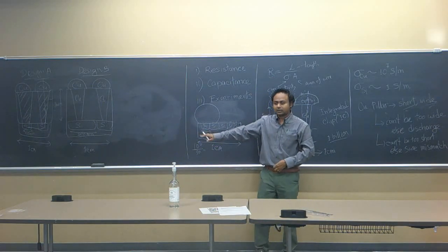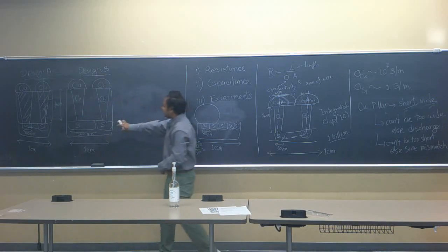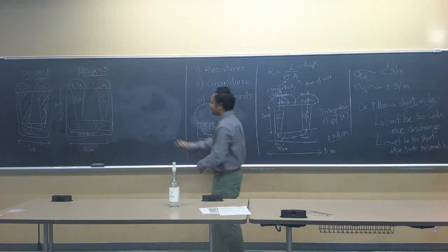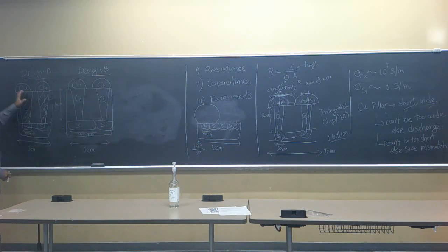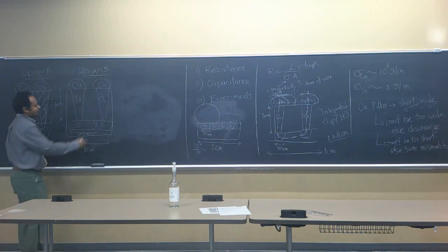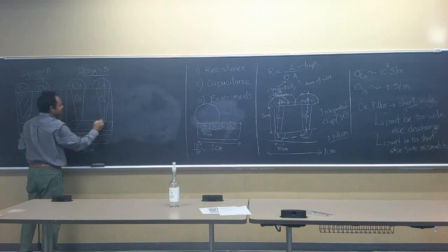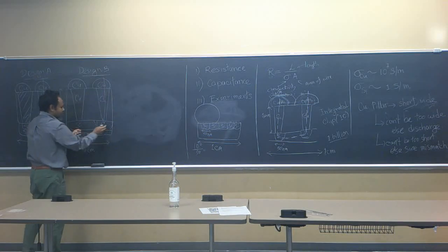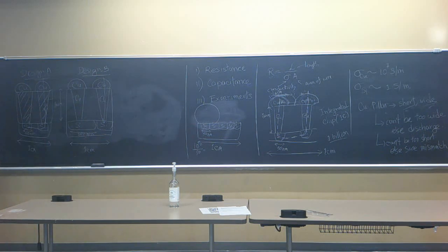Understand? So I think this is one question which probably many of you missed in the exam, which is okay. I mean, you are just learning this stuff. So here is, one more time, that we are trying to minimize the resistance of the entire IC system, and that's why we have to make sure that each of these devices has as minimum resistance as possible. So whenever current goes to the copper pillar, you want to make this copper pillar very short, very wide. You have to make this silicon device very small, so that the eventual resistance becomes minimum.